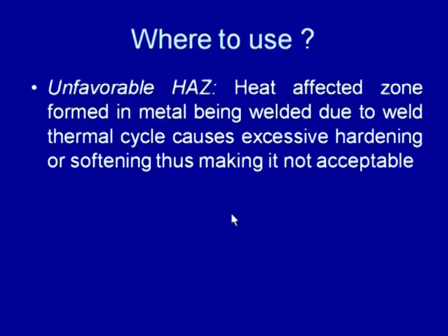Under those conditions, brazing and soldering is found to be effective for developing a joint because it supplies very little heat. So, these adverse effects related to fusion welding processes can be avoided by use of brazing, soldering and braze welding processes.